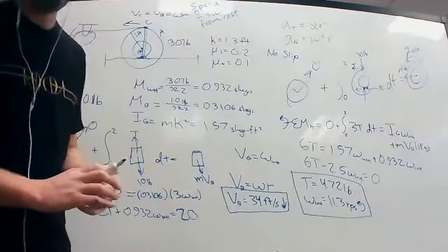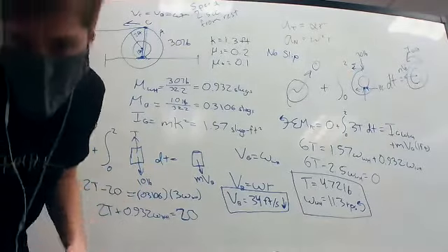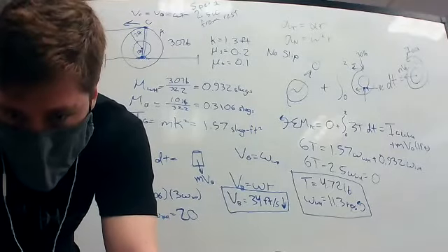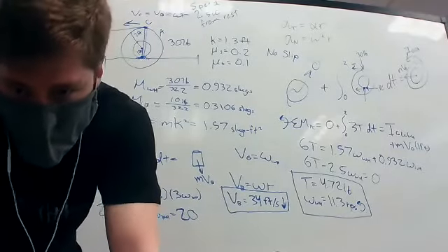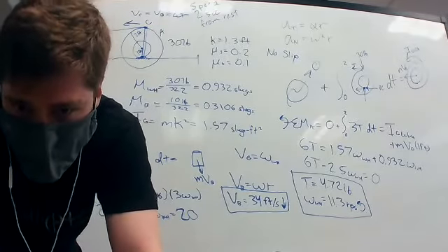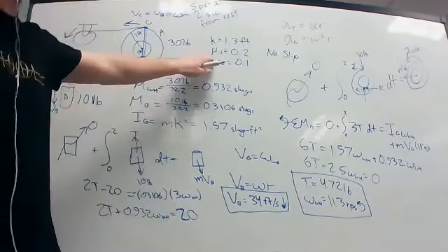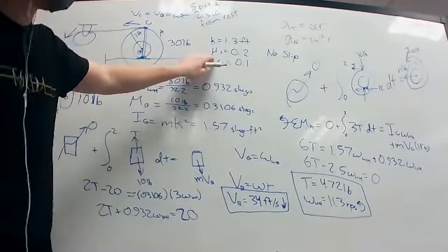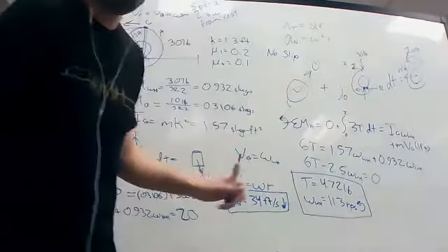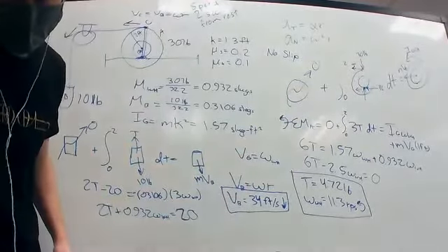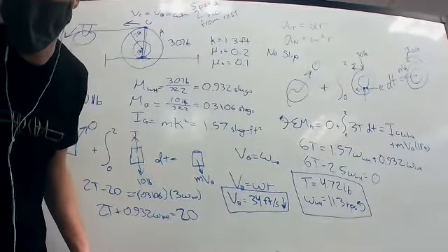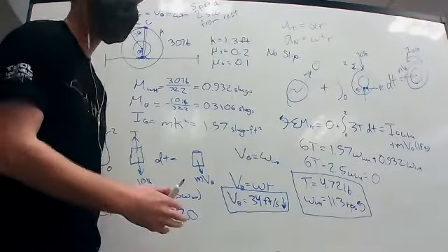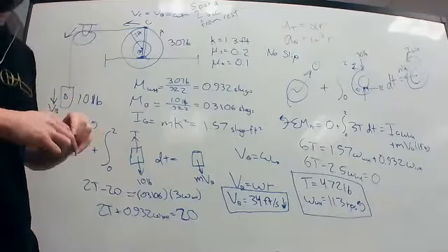So plugging in the values, we would just be checking to see if the friction was greater than F max. So the friction that you would find in this problem would be 0.55 pounds, and F max would be our mu sub s times the normal force, which is just going to be equal to the weight. And so the friction force you would find is 0.55 pounds, which is less than the friction max, which is 6. Therefore, our no-slip assumption is good. Any questions on this problem?